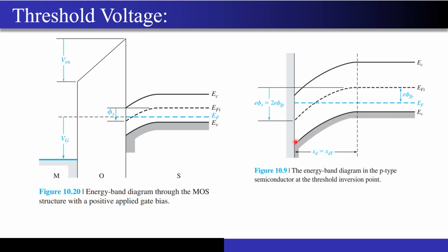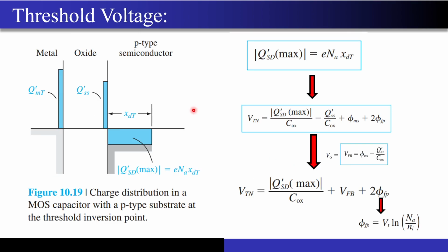So now this was the basics that we actually require, and we had also seen some formulas, right? So now this was the charge density diagram that sir must have told you. If I am applying a positive voltage at the metal, I have created a positive charge density over here at the metal end. So somewhere I have to bring this negative charge density, which will have the same magnitude as the positive charge density that I have brought at the metal, right? Now you just ignore this term, this Qss dash, as of now.